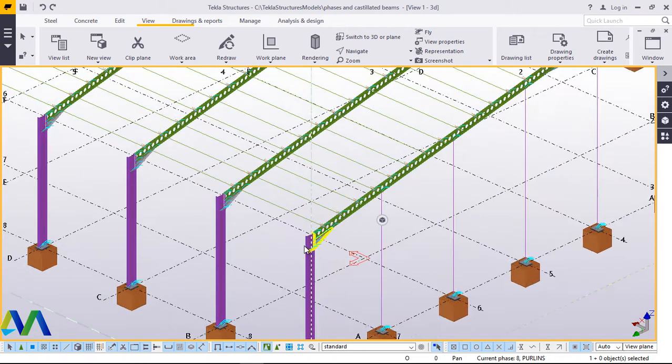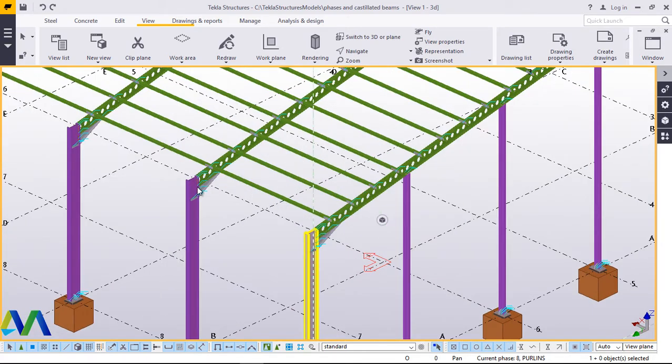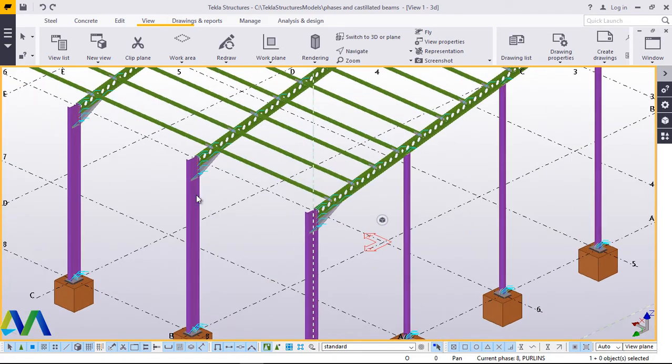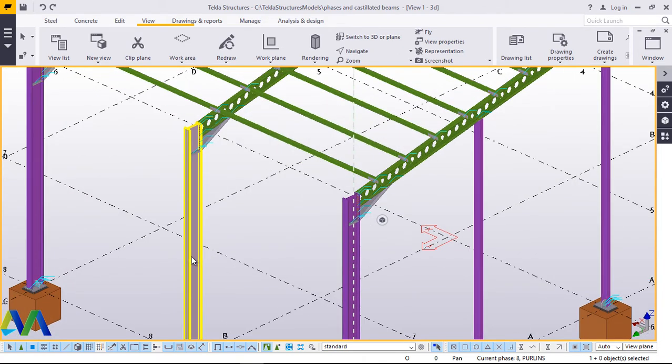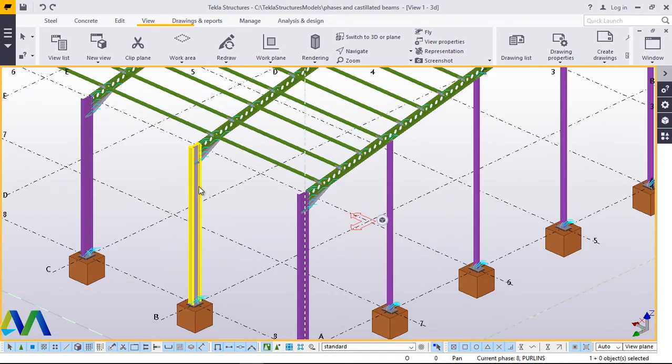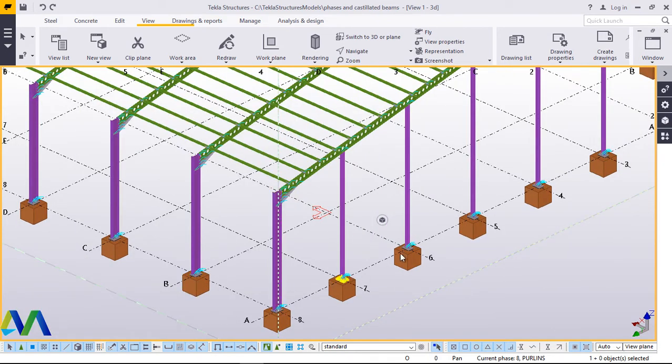Now, this is our previous model, and I want to add a tie beam here and bracings and stub plates that will help us in supporting and providing a seat for our RC beams prior to placement of the masonry wall beneath the RC beam.